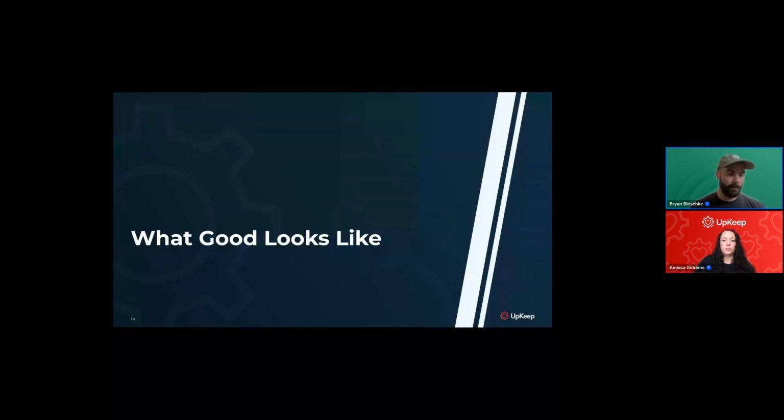What does good look like? This isn't a question. You can respond if you'd like, but how many of you have actually been told or shown how your machine should be operating in its defined context? Who has said, I'm making up a name, Jimmy, this is the way this bottling line should function from start to finish. This is how this sensor works and it trips, this is how the conveyor works. We should get this many bottles off the line in this amount of time. This gearbox takes ISO 46 fluid. It should spin at 700 RPMs. These are the type of bearings. How many of you have actually even had that told to you?